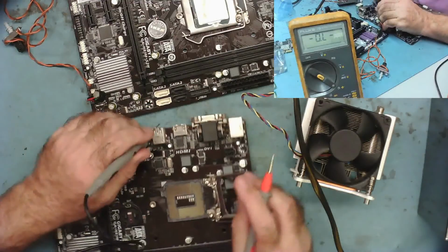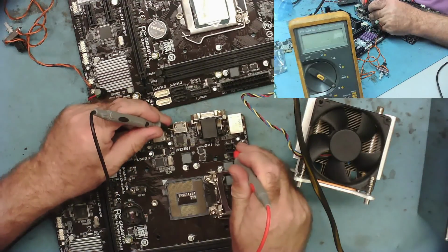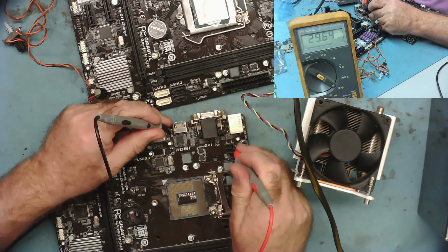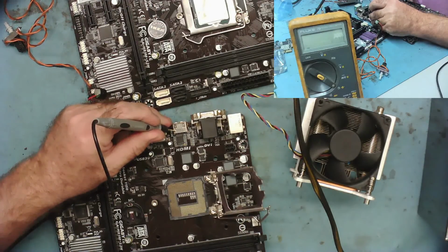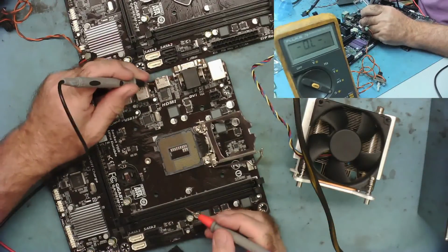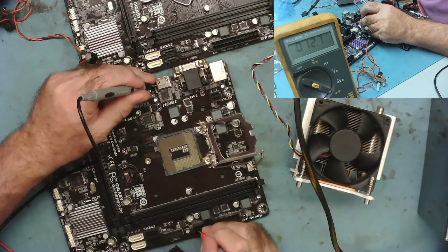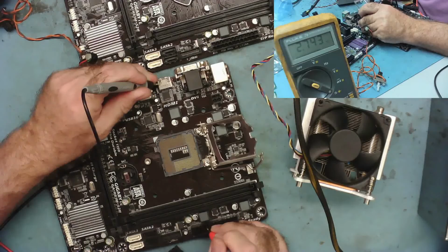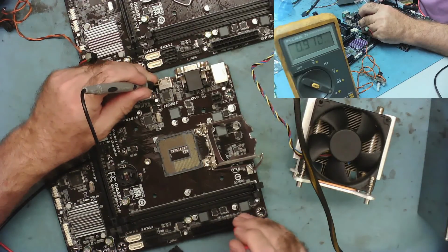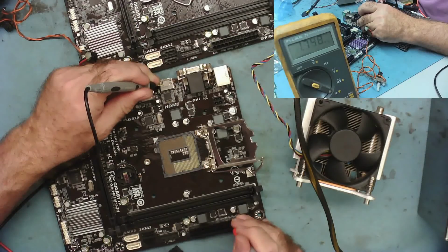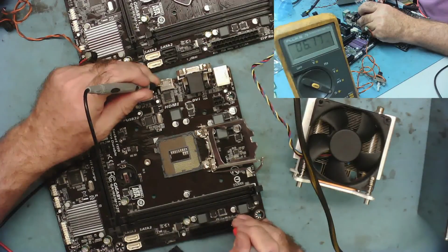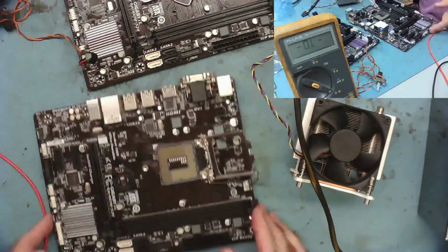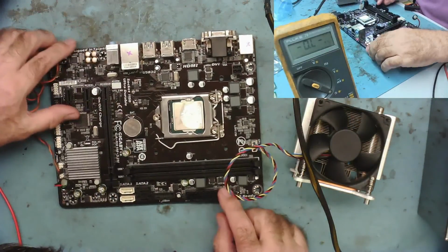Okay, so on this one, same sort of thing. 3.3 volts, sorry, just off the edge of the picture, 3.3 was about 12 ohms. One, two, three, fourth one in is a 5 volt, 2.7, basically the same. And the second one in here, we get this kind of like what we had before. So that's fine, and then it starts going up again. So there's no difference there. It appears to me that basically this one is signalling the power supply to switch off and on.